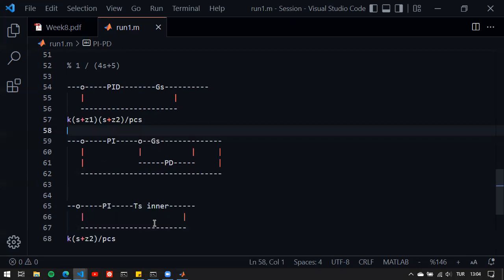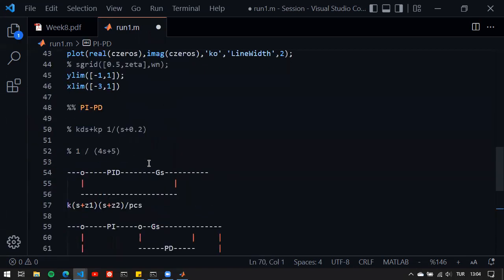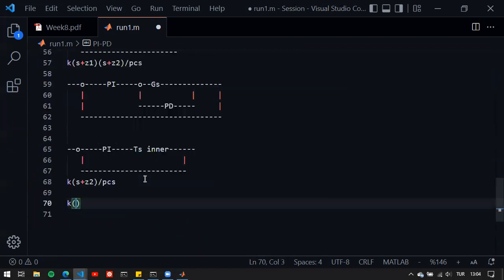because you have to keep 1 zero away from the dominant region. So that's nice. But that's not all of it. We still have something left here. We did get rid of the zero, but what about this zero here? Note that the PI controller is left, and here somewhere, did I remove it? Seems like it. Here somewhere, I've talked about the fact that we can use S plus Z1, and then K2 times S plus Z2.